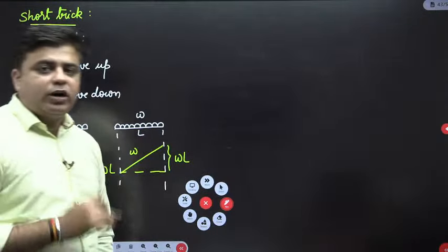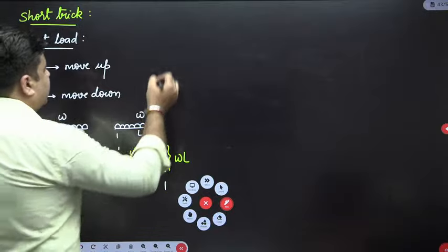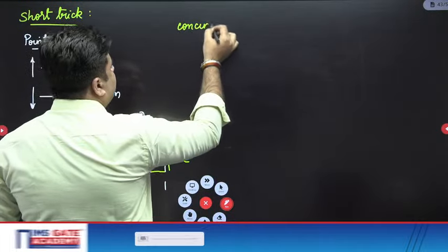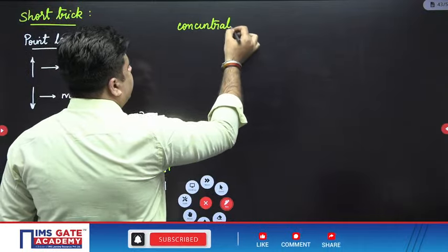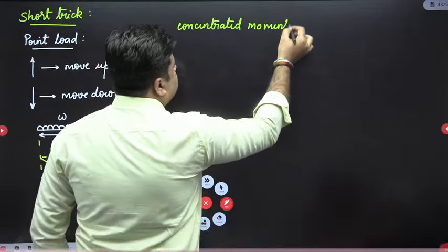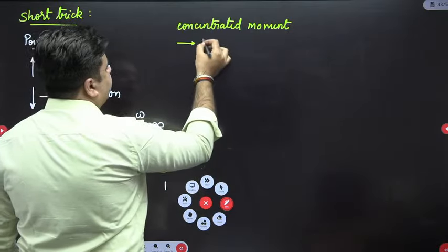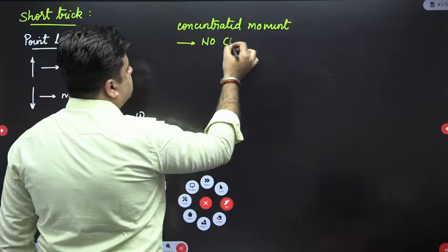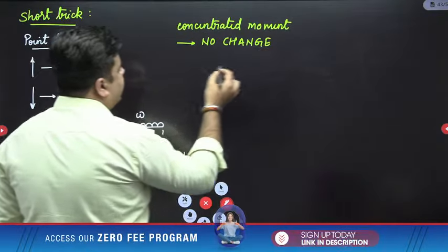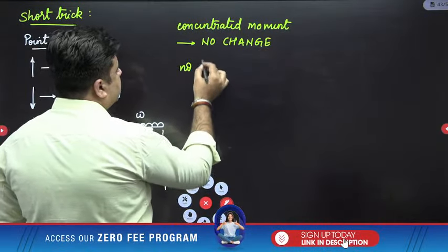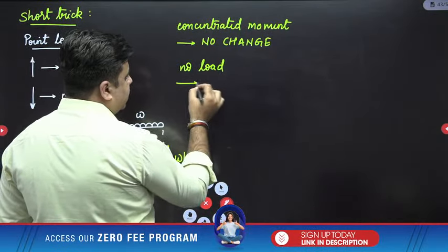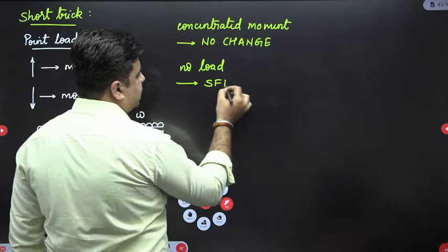The next important point is whenever a concentrated moment is acting, there will be no change in the shear force diagram. And when there is no load acting over a span, then the shear force diagram will be constant.